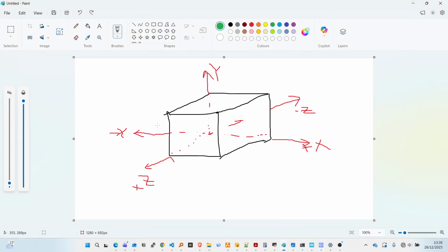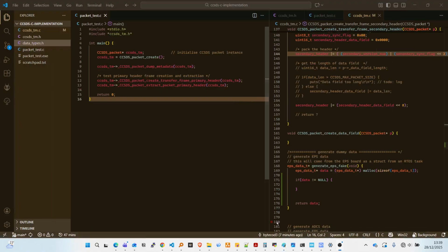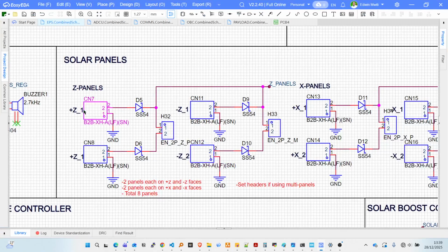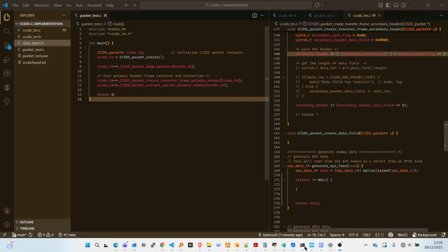Considering this CubeSat is 100 by 100 millimeters, a 1U, 90 by 90 will fit somewhere around here with an allowance of at most 1 centimeter on all the sides. So if I buy the 90 by 90 ones, I can fit one panel on one side. Other panels that I found were like half of that.